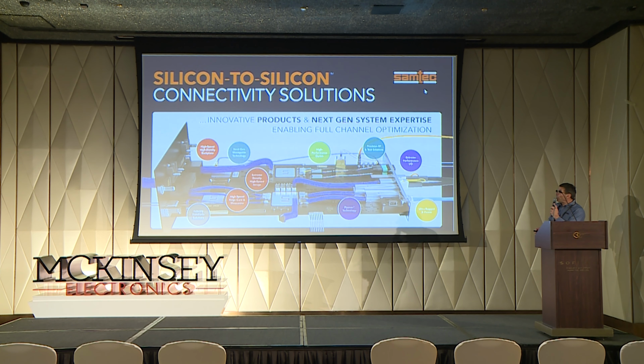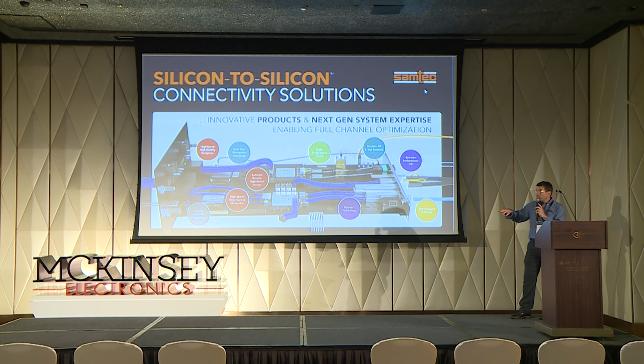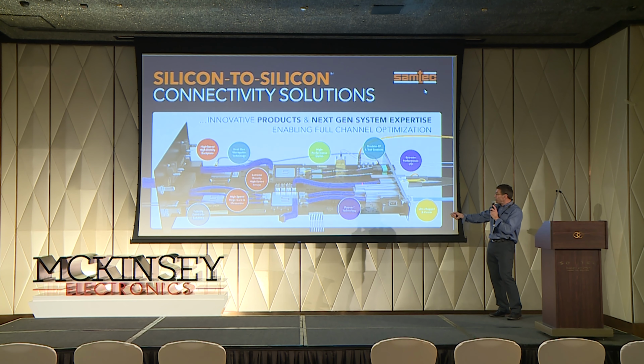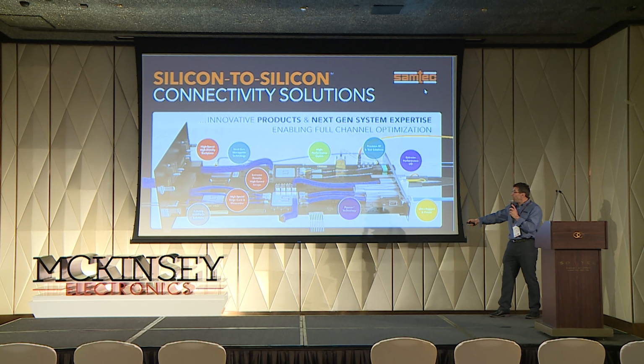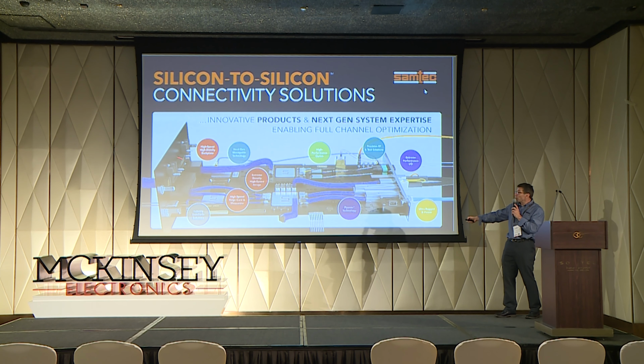Looking at high-speed cables, really we're thinking inside the box. Everything here for these blue cables is running from your AI, FPGA, or high-performance processor in the middle. We're taking the high-speed lanes straight out to the front panel, which could be QSFP-DD, DD800, OSFP, or to a backplane.